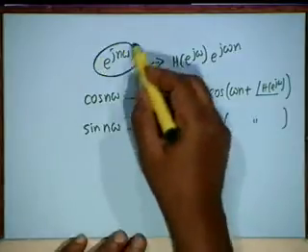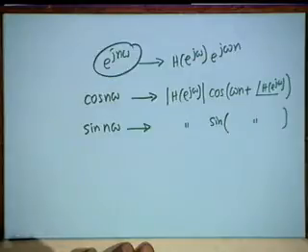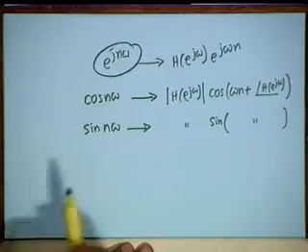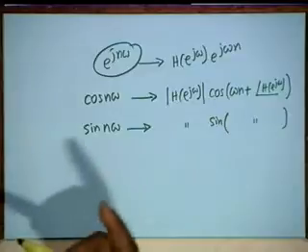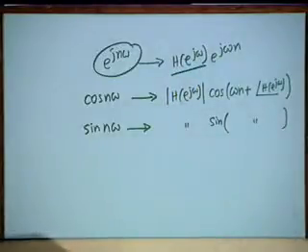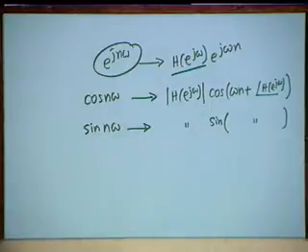So, this signal is the most important signal in practice. In the time domain, what is the most important signal? Delta n. Because if you know h of n, then you know the total characteristic of the system. Correspondingly, in the frequency domain, it is e to the j n omega. If you know the response to e to the j n omega, or you know H of e to the j omega, they are equivalent characterizations.